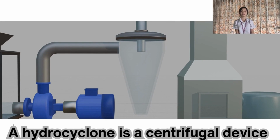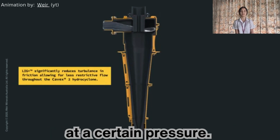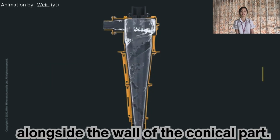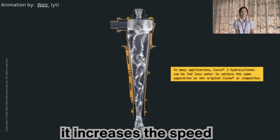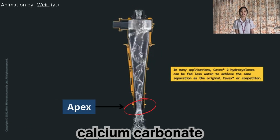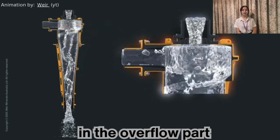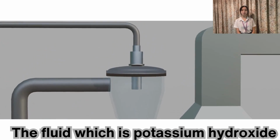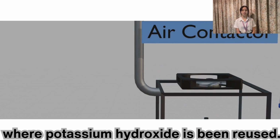A hydrocyclone is a centrifugal device used to separate solid from the bulk fluid. The mixture is fed into the hydrocyclone tangentially at a certain pressure. This creates a centrifugal movement, pushing the heavier phase outwards and downwards alongside the wall of the conical part. As the diameter of the conical part decreases, it increases the speed and so enhances the separation. Finally, the concentrated solid, which is calcium carbonate, is discharged through the apex and transferred into the calciner, while the vortex finder in the overflow part creates a fast rotating upward spiral movement of fluid in the center of the conically shaped housing. The fluid, which is potassium hydroxide, is discharged through the overflow outlet, linking to the air contactor system where potassium hydroxide is reused.